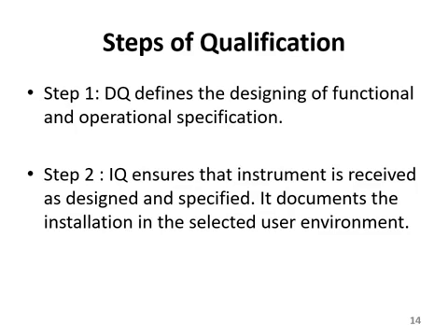Step 2, installation qualification, IQ, ensures that the balance or instrument is received as designed and specified, right? So in installation qualification, as a second step after design qualification, you need to know how the process or the product was designed, and when you are receiving it, is it in the same condition it was designed and specified.